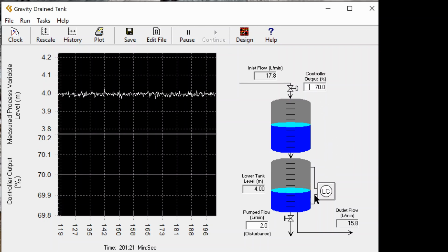So now we need to check what the control configuration is here. The objective is to maintain the level of liquid in tank 2. Now by manipulating what? If you look at this one outlet, for this case it is identified as a disturbance, and there is no valve here. So just by common sense, the only valve that you can manipulate is here. So the control configuration should be such that the output is the level of liquid in tank 2 and the input is the flow rate into tank 1.